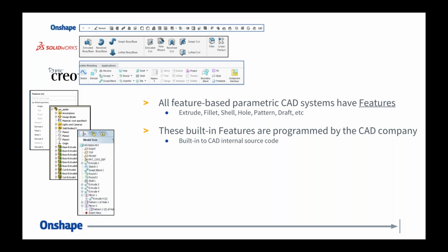So in Onshape, you can literally look at the extrude source code, the revolve source code. So the reason that's really critical is because a lot of what you may want to build is building on top of those standard building blocks, right? I want to automate a process. That process is, I want to draw out this sketch and I want to revolve this profile. Well, I can easily cut and paste sections of Onshape source code into my own variation of that command, right?